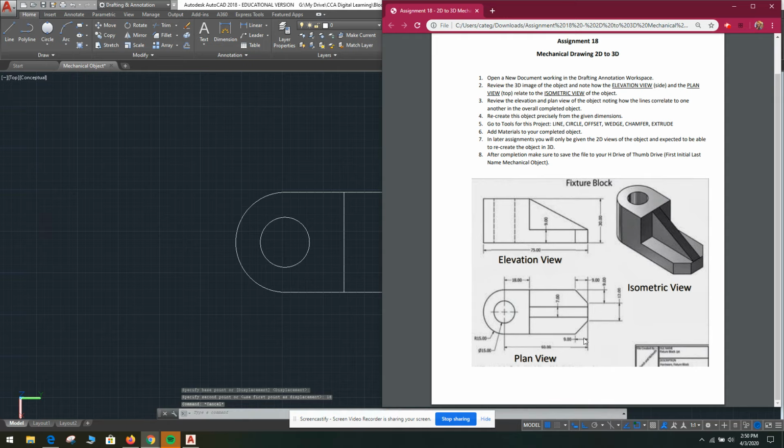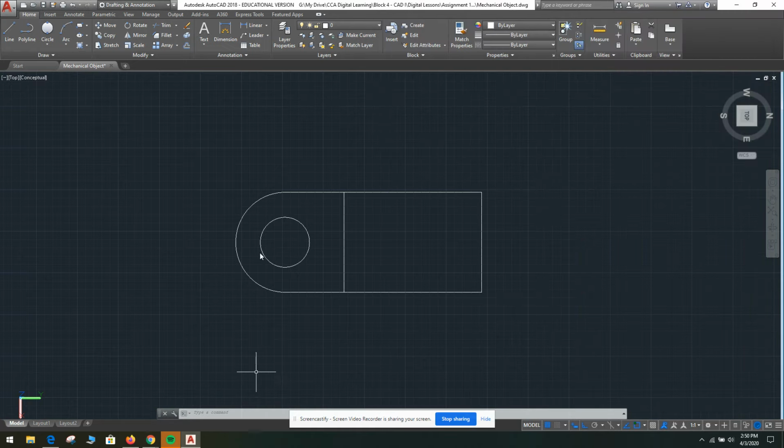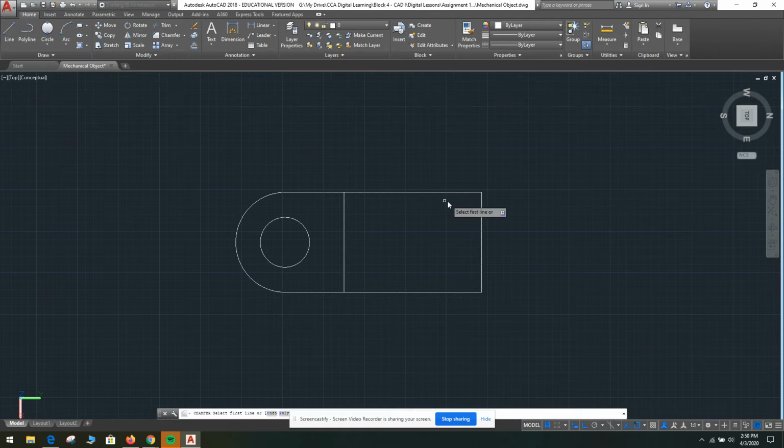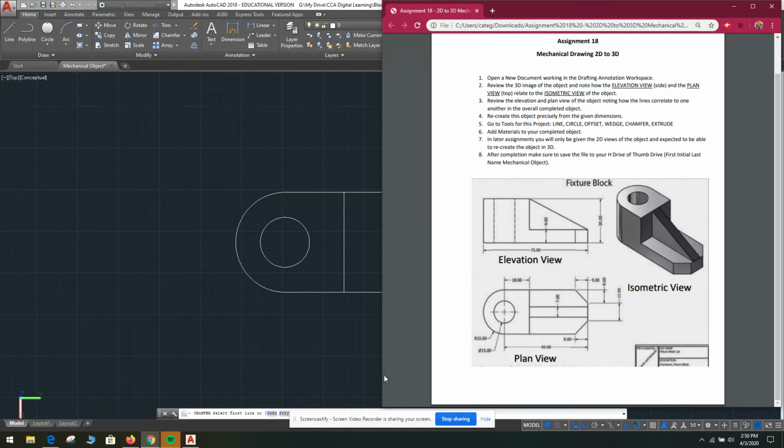Okay, so the next thing I need to make on this footprint are these two chamfered edges. Okay, so think back to your chamfer tool. It's underneath fillet up here at the top, and you'll hit chamfer. Now, if you look at your image, okay, it's equidistant, equally cut back on the width, equally cut back on the length.